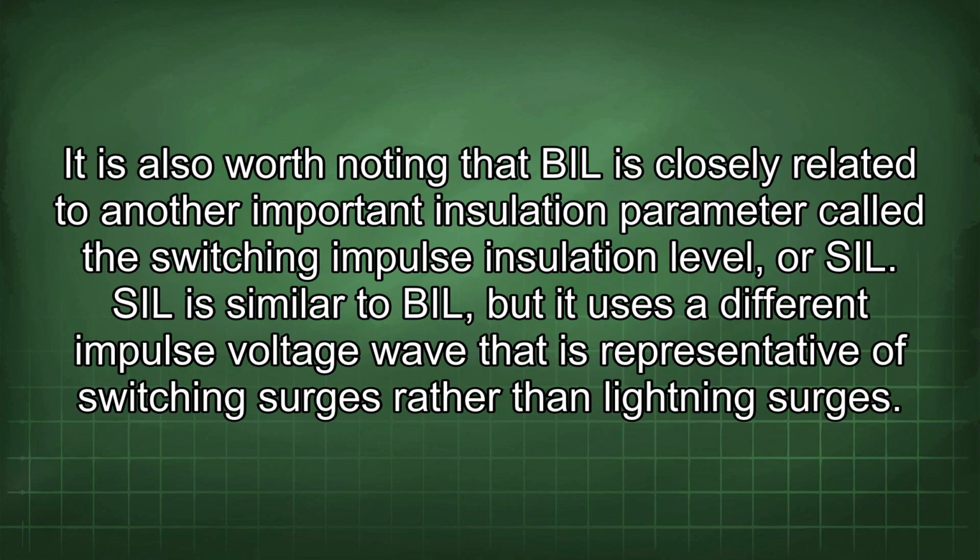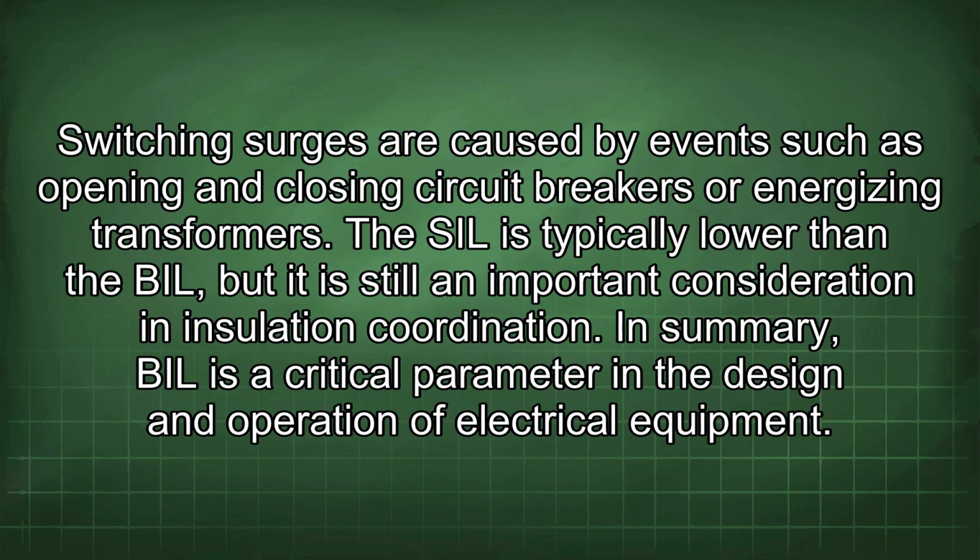It is also worth noting that BIL is closely related to another important insulation parameter called the switching impulse insulation level, or SIL. SIL is similar to BIL, but it uses a different impulse voltage wave that is representative of switching surges rather than lightning surges. Switching surges are caused by events such as opening and closing circuit breakers or energizing transformers. The SIL is typically lower than the BIL, but it is still an important consideration in insulation coordination.